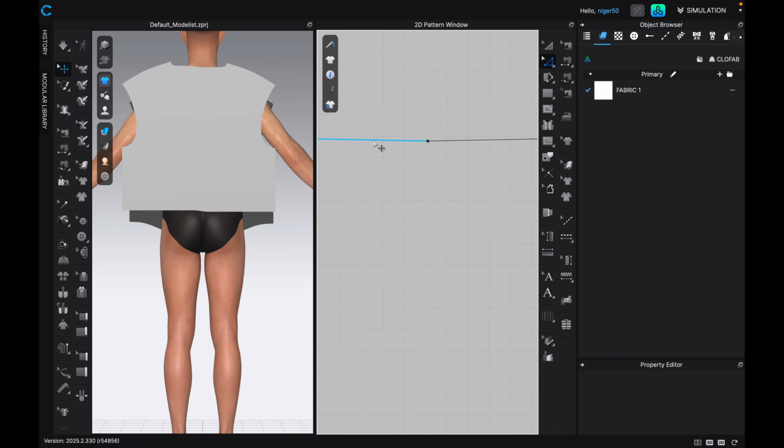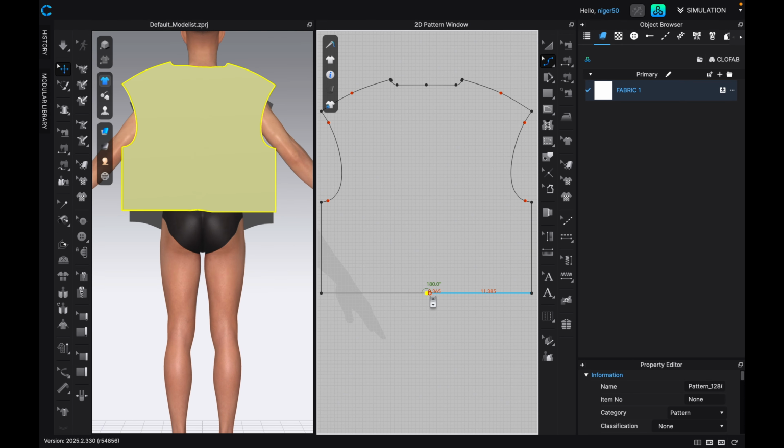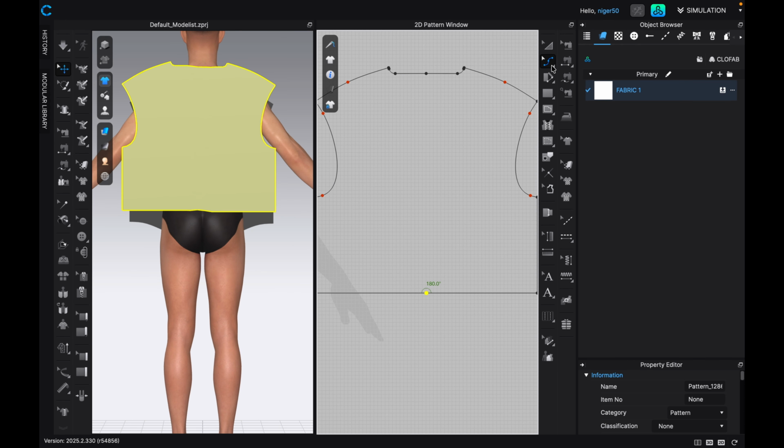As you can see, this is not straight because we have joined the 2. You can still leave it like this, but I don't like to have this kind of pointy edge. How can we get rid of this? We're going to get rid of it by clicking on Z. And I want to put this to curve.